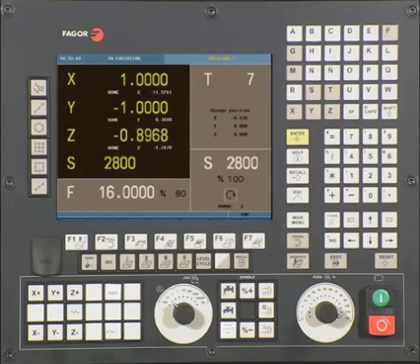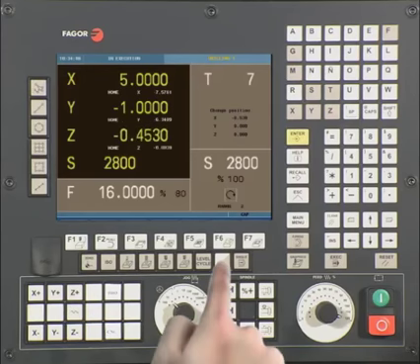If gear ranges are an option on your machine, you may be prompted to change to the correct gear, change gear, and press Enter to continue. Slowly turn up the feed rate so the execution can continue. To see additional information while the program is being executed, use the half key to toggle between basic and advanced screen.